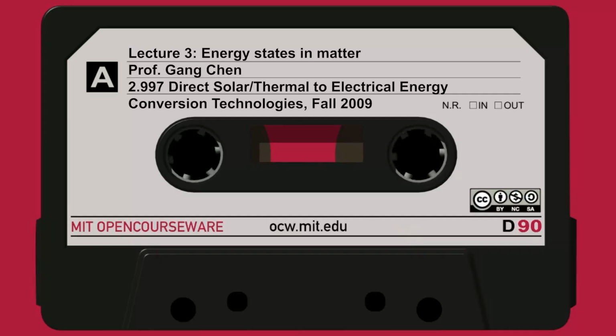And that's the intrinsic silicon I said, right? But you could even put impurities into silicon, into semiconductors, to add more electrons or add more holes. So for example, if I put phosphorus in silicon, phosphorus has 5 charge. Silicon has 4 in the outer shell. So there's one extra compared to silicon. So that extra electron, because the energy level of phosphorus is very close to here, can easily be excited to this region. So it's an N-type semiconductor.